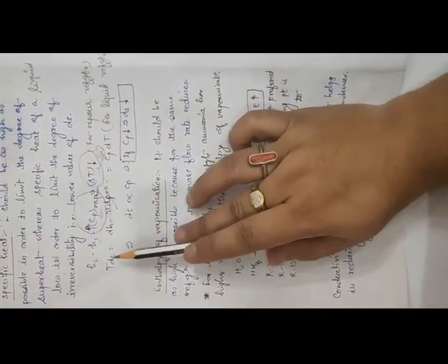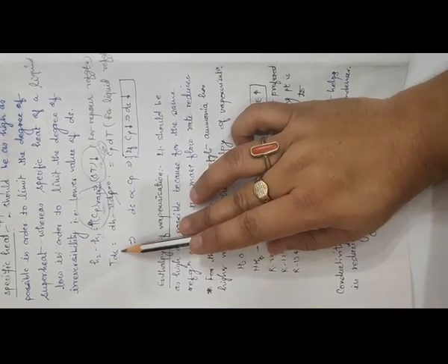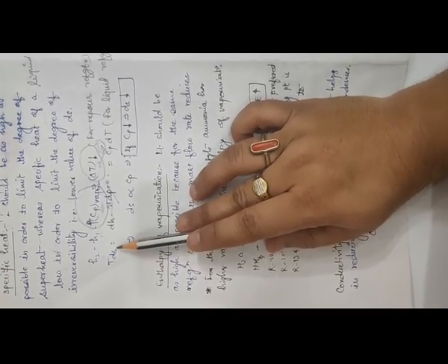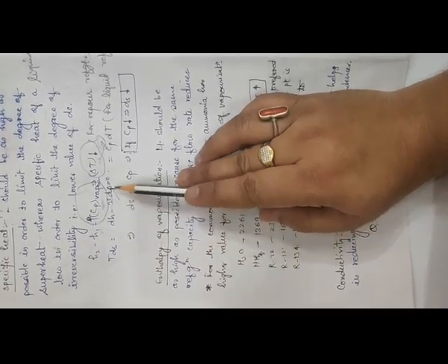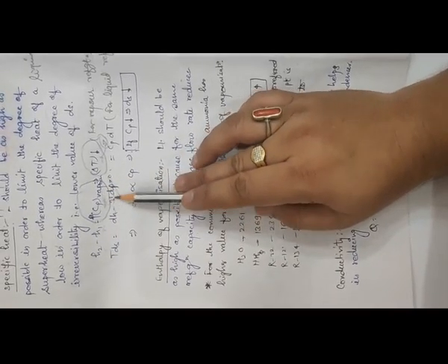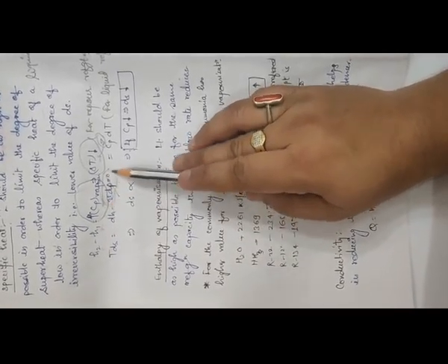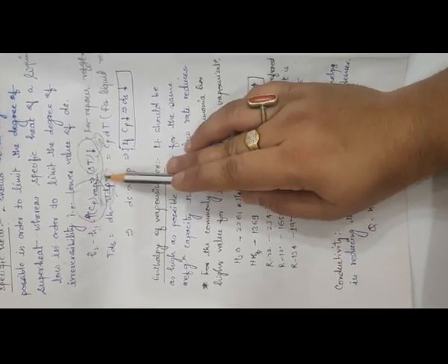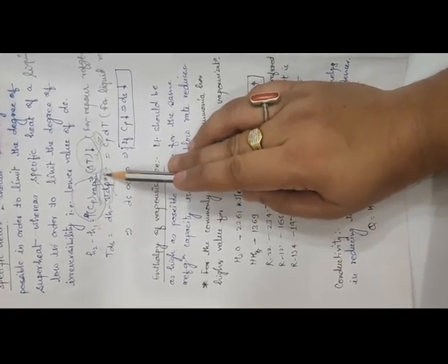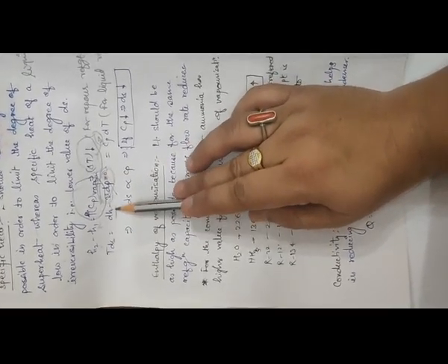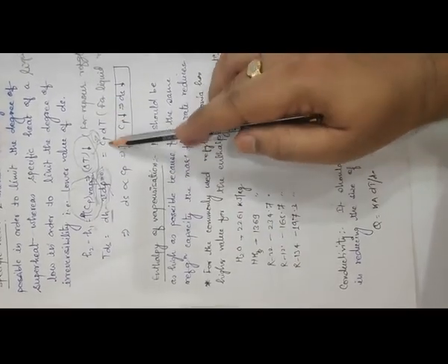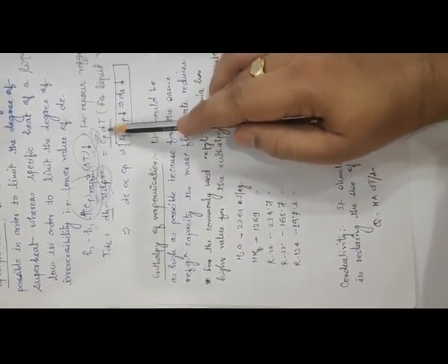Here we can understand by this one that the TdS equation can be written as dH minus VdP. If the pressure is constant, this term becomes 0 because change in pressure is 0. Now dH, the enthalpy difference, can be directly written in terms of temperature as Cp dT.